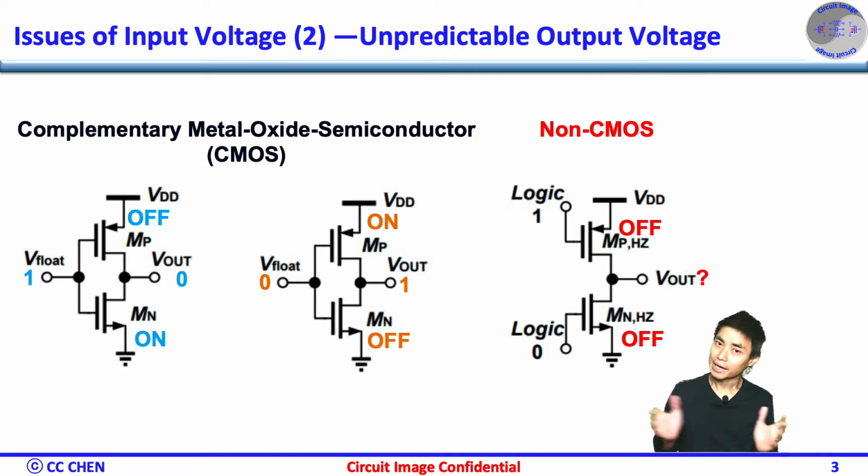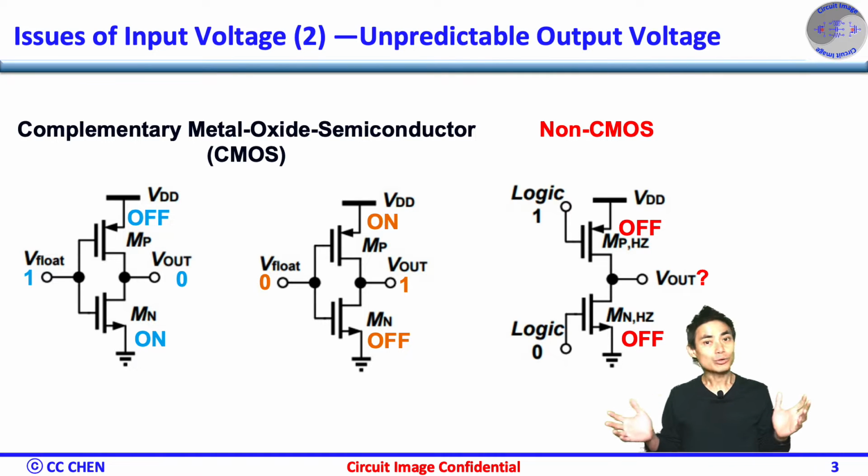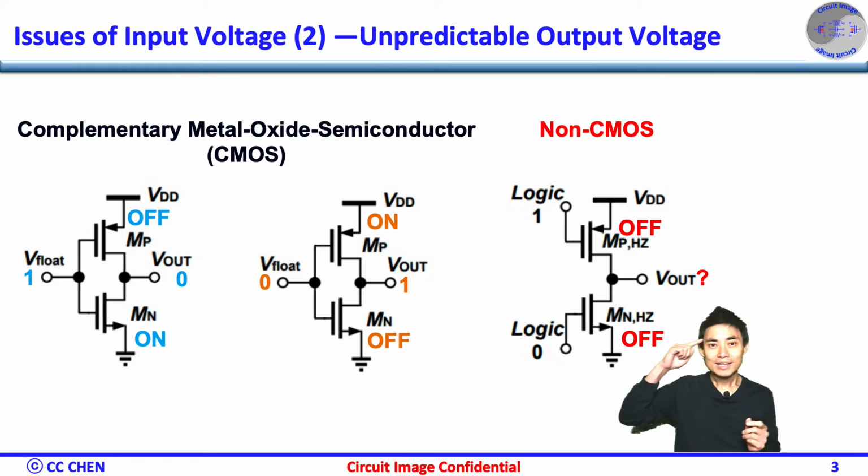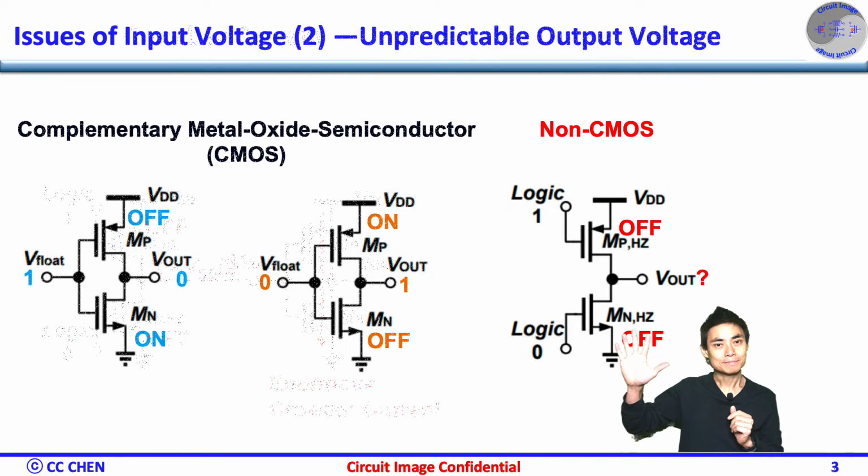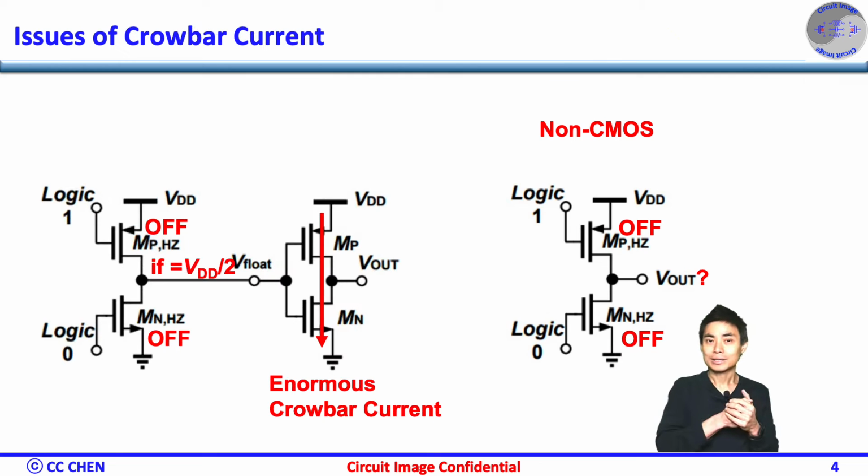If this is the case, do you see any reliability issue? Think about the buffer chain image for 5 seconds. Correct. This inverter will connect to another inverter. So, the floating output will be the next inverter's input floating gate.